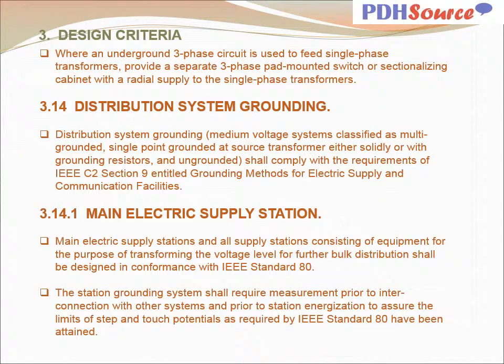Where an underground 3-phase circuit is used to feed single-phase transformers, provide a separate 3-phase pad-mounted switch or sectionalizing cabinet with a radial supply to the single-phase transformers.